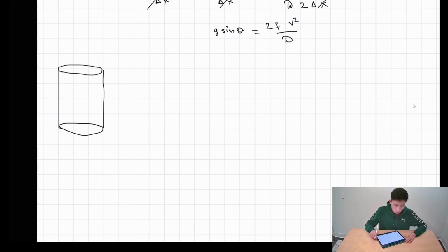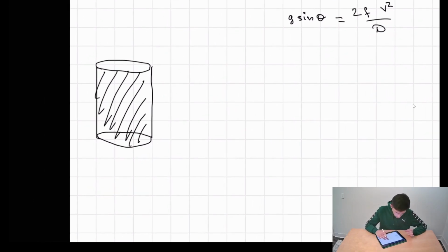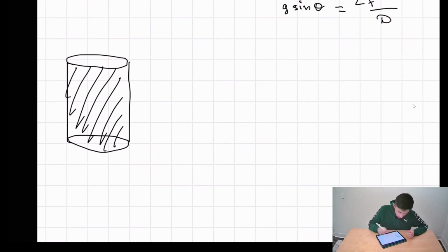which is in our case water. So we have a fluid inside, right? Okay, so let's try to do the force balance for our particular case. So it's going to have a weight, right? The weight is mass times the gravitational acceleration. And we can also express our mass in terms of height multiplied by the cross-sectional area, right?